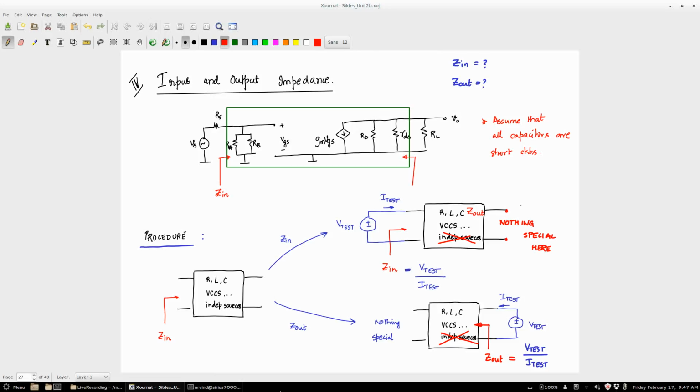So we will look at other topologies where you can reach some of these trade-offs. Okay. So for any amplifier topology, you have to remember these things. What is its gain? Is it high, low? What is its input impedance? Is it high, low? What's its output impedance? High, low? How is its frequency response? And what are its swing limits? Okay, that's what you should know for all the topologies that we will be doing.